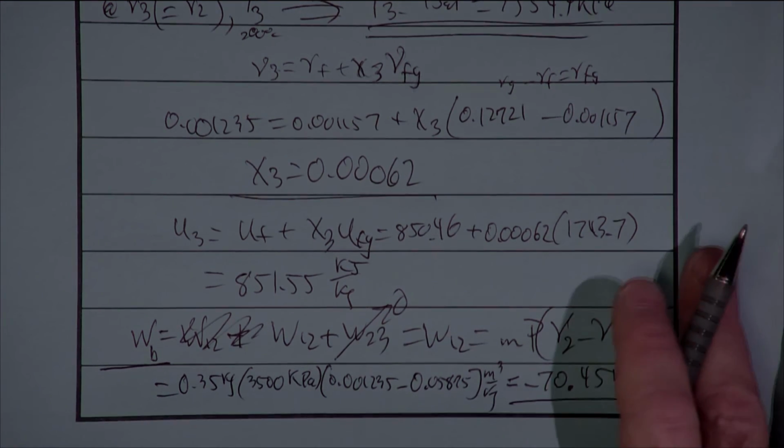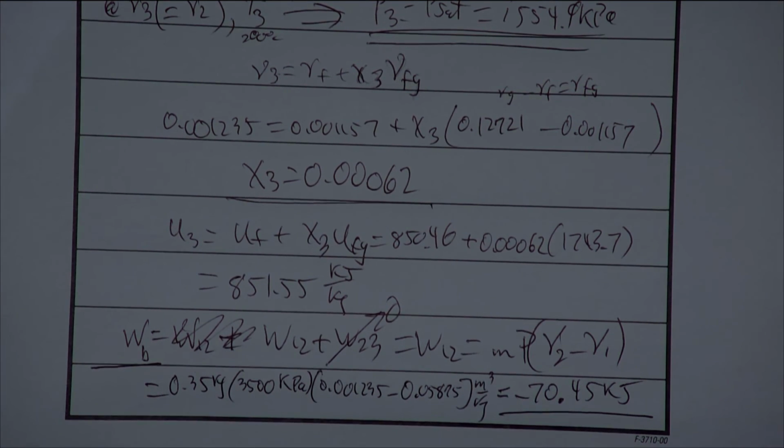Now, before we move on, does the minus sign make sense? Well, it should, right? Negative work means work is being done to the system. In other words, the piston is pushing into the system. Work is clearly being done to the system. The volume is shrinking. So yes, the negative sign is proper.